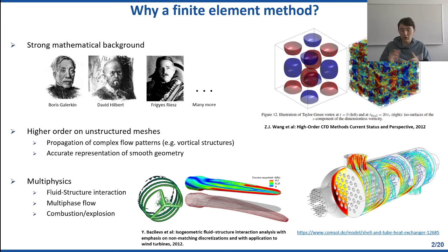This is from a COMSOL website, where it's interfaced with the heat equation. So we're interested in transporting heat. And so then we have multiple types of physics, and even though the finite volume method is very good at handling fluid mechanics equations, we typically don't use the finite volume method for solid mechanics. That's where finite elements dominate. So finite element methods have the strength of being able to handle all kinds of equations, and in this sense are very suitable for multiphysics applications.